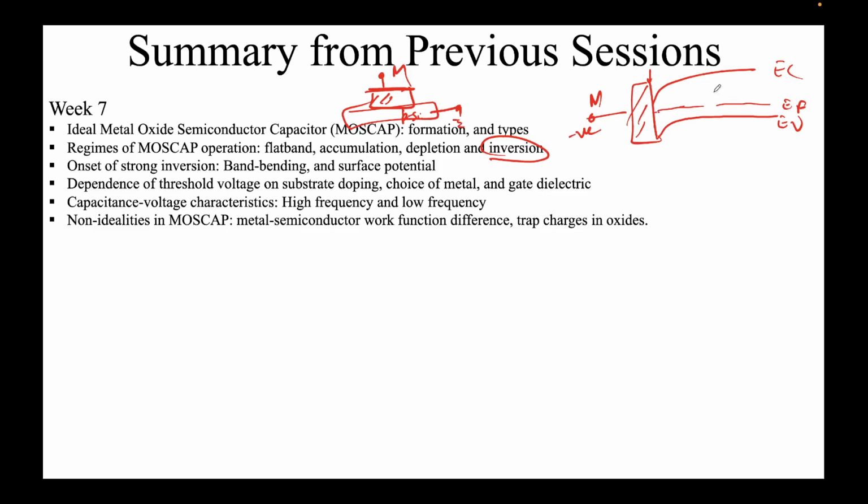It depends on the doping of the substrate naturally, and the metal choice, because that dictates the semiconductor work function, and the gate dielectric, it should be perfect and no trap charges and so on.